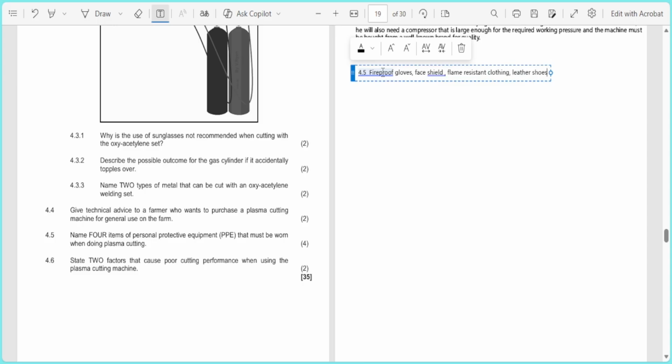So we are dealing with plasma cutting. Plasma arcs can reach very high temperatures. Imagine sticking your finger into such temperatures. You're going to burn right there and then. That's hotter than the sun's surface. So regular workshop gloves won't cut it. The face shield protects not just from sparks but from the UV radiation coming from the plasma.